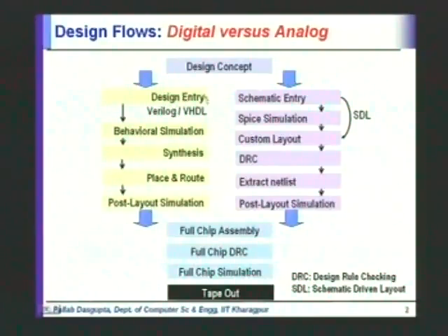Now this design entry in the digital designs is typically in some language like Verilog or VHDL, and then to make sure that the entered design is correct and meets the original design intent, we do what is called behavioral simulation. The simulation runs that code written in Verilog or VHDL with appropriate tests and checks whether the output that the simulation produces matches your expected output.